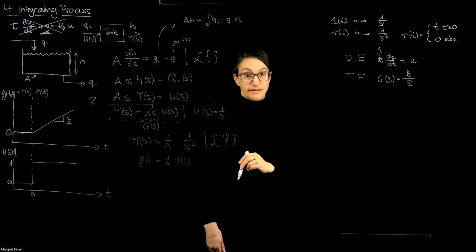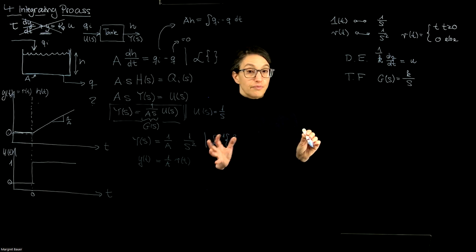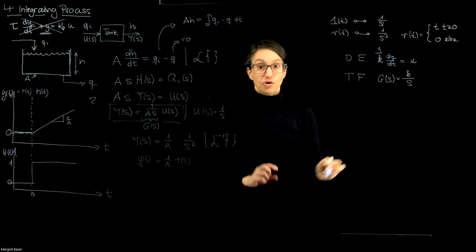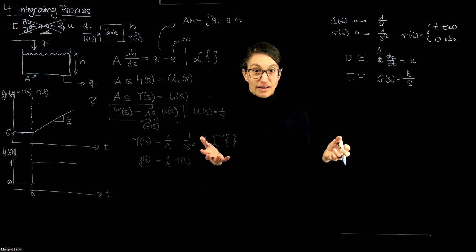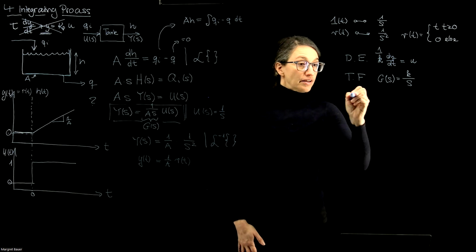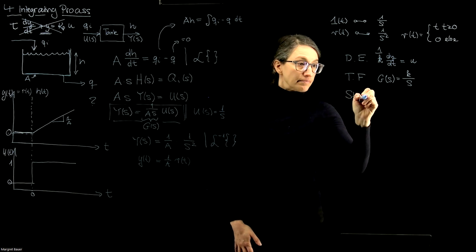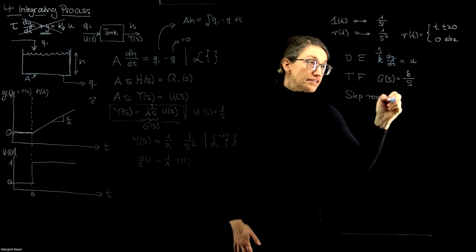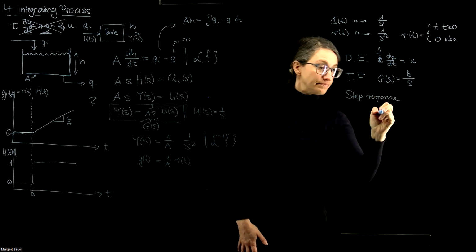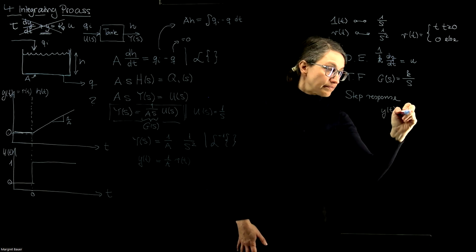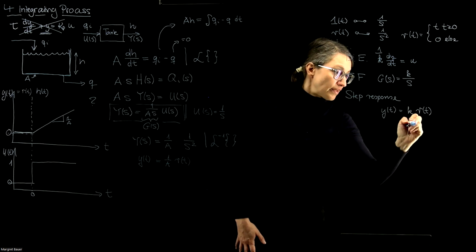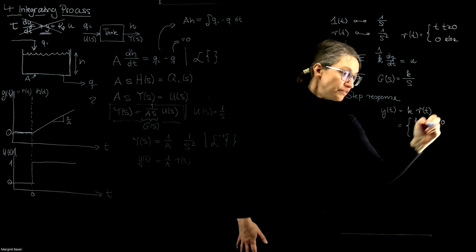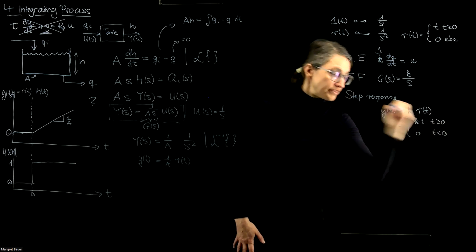This is our integrator. Don't confuse it with a signal. We can't do the inverse Laplace transform of a transfer function. We can only do the inverse Laplace transform of a signal. And our signal is y of s. So the step response of an integrating process is r of t, equals k times t for t greater than 0, and 0 for t smaller than 0.